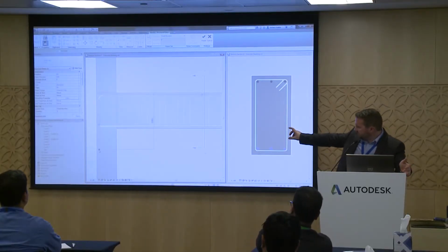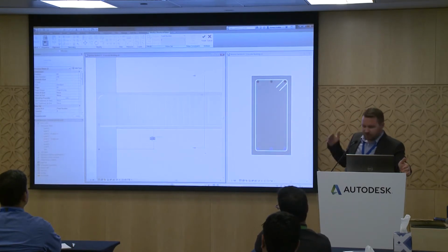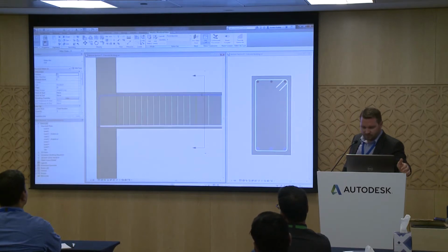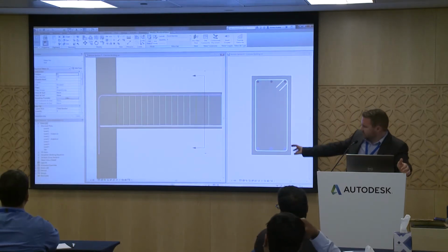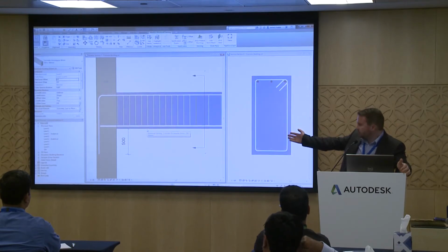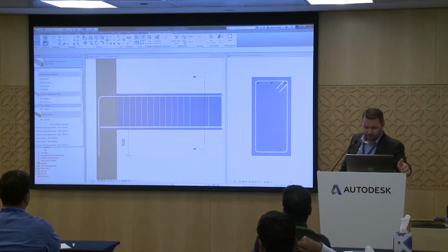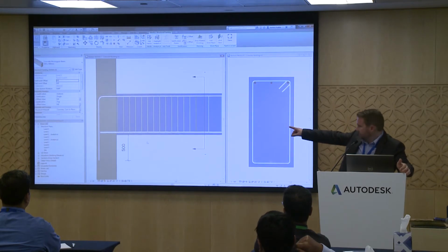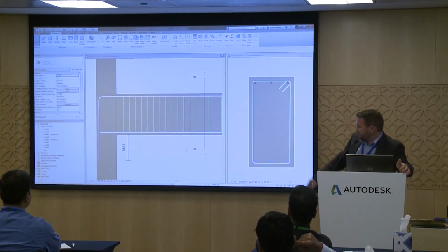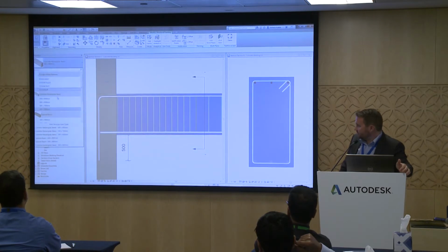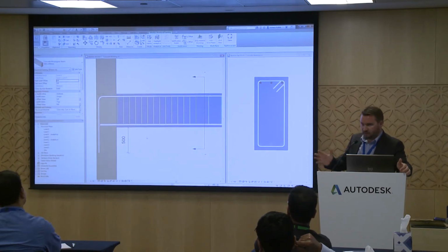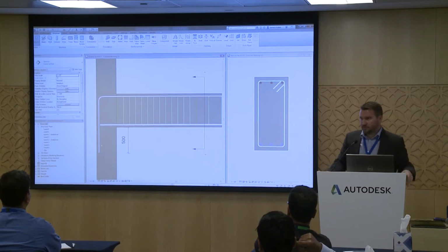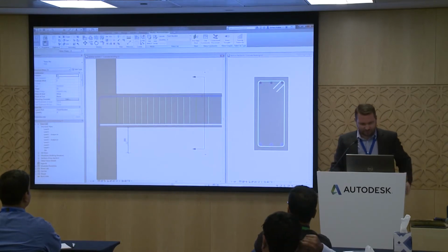So now this distance I want to be always the same. So I put the distance I want, I validate. And since it's the bottom of the beam, if I change the beam, my rebar will move. Okay. So the stirrup will move and the length will move. I change from one side to another side and everything is moved. But as you know, it's not a surprise, we are in beam.